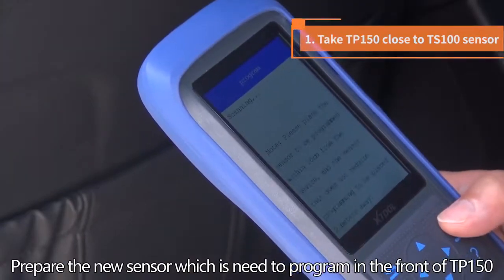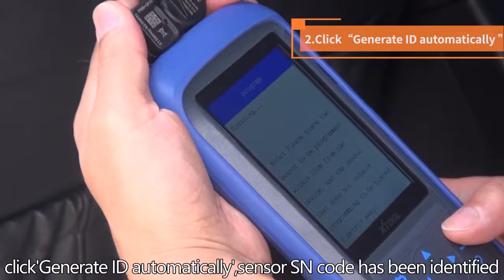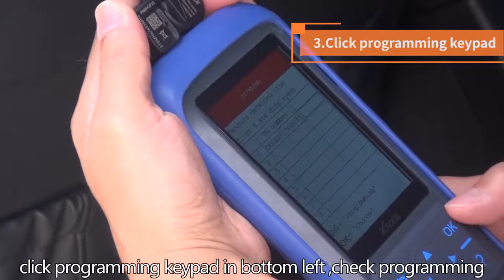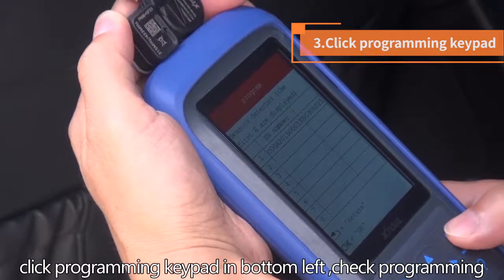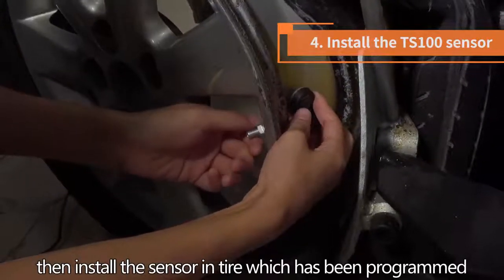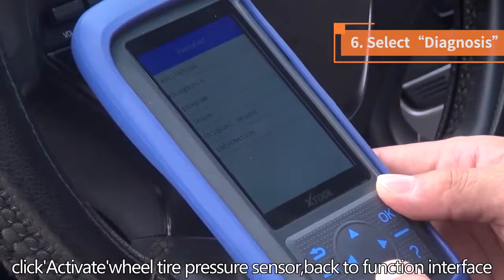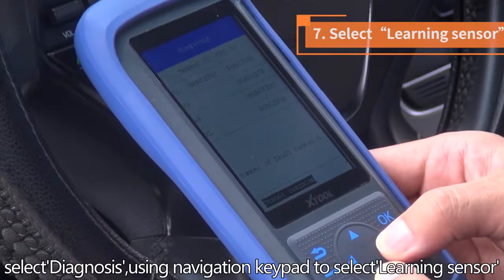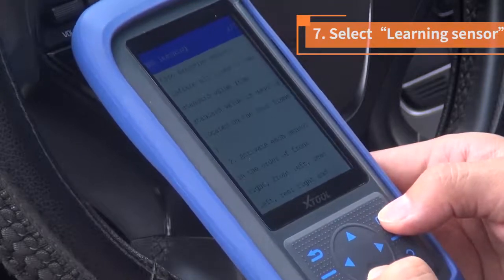Prepare the new sensor which needs to be programmed in front of TP150. Click Generate ID automatically. Sensor SN code has been identified. Click Programming keypad in bottom left. Check Programming. Then install the sensor in the tire which has been programmed. Click Activate Wheel Tire Pressure Sensor. Back to function interface, select Diagnosis, using navigation keypad to select Learning Sensor. View the hint to learn sensor.